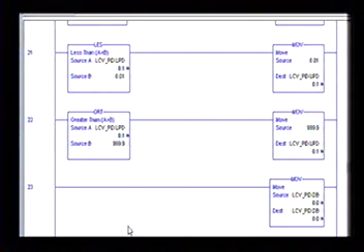Because if these values fall outside of these ranges, what I'll do is go through and type in the min and the max values on all the OIT's inputs to make sure that I can't fault this processor. And as long as I can't fault the processor, neither can the operator, right? There's nothing invalid coming in. Even if the OIT was programmed wrong, or somebody got in there and started playing with it and was able to change the min and max value that the OIT could enter, the PLC would have the last level of correction or data validation and say, no, we're not going to allow that. We're going to move it back to the proper value.